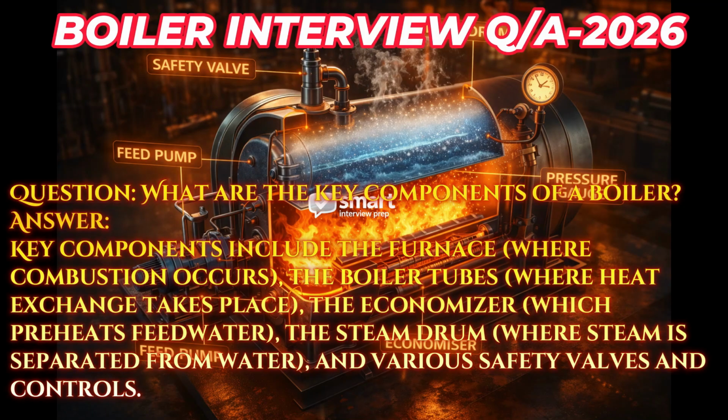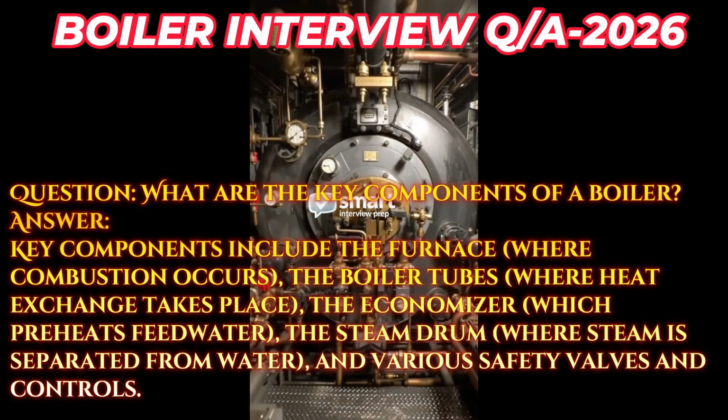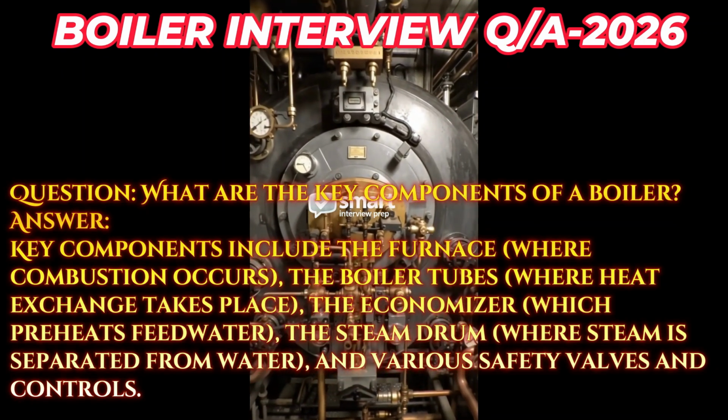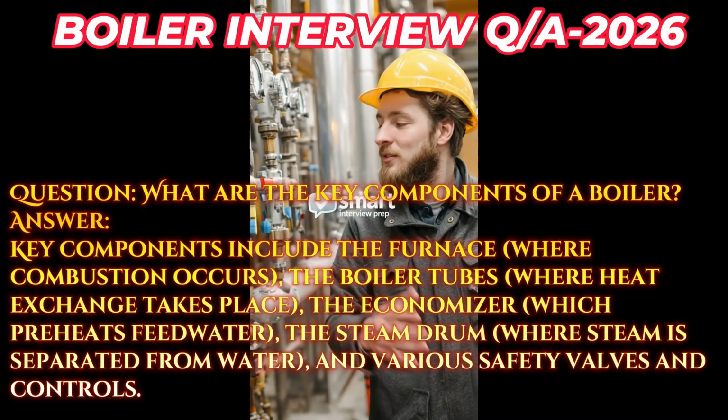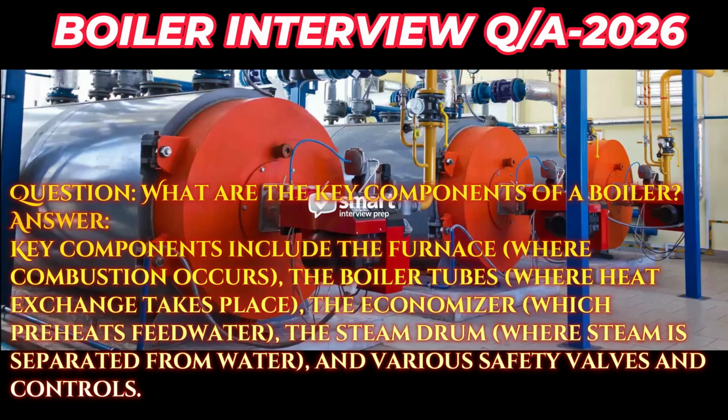Question: what are the key components of a boiler? Answer: key components include the furnace, where combustion occurs, the boiler tubes, where heat exchange takes place, the economizer, which preheats feed water, the steam drum, where steam is separated from water, and various safety valves and controls.